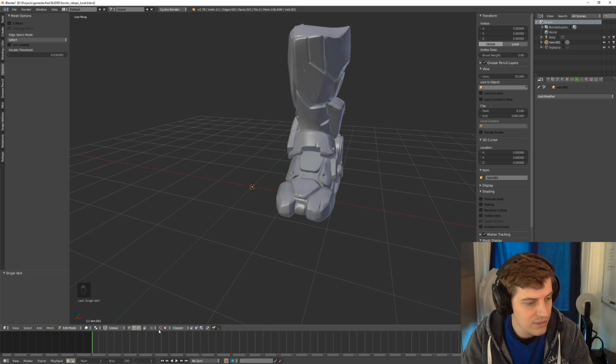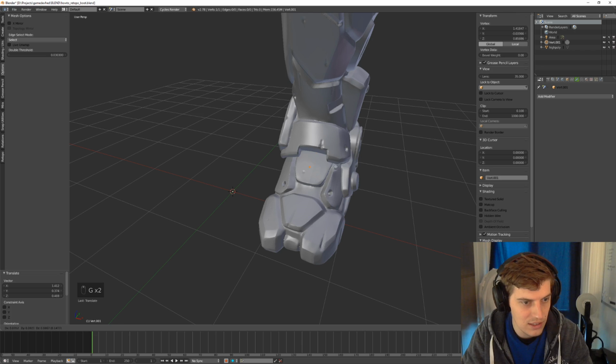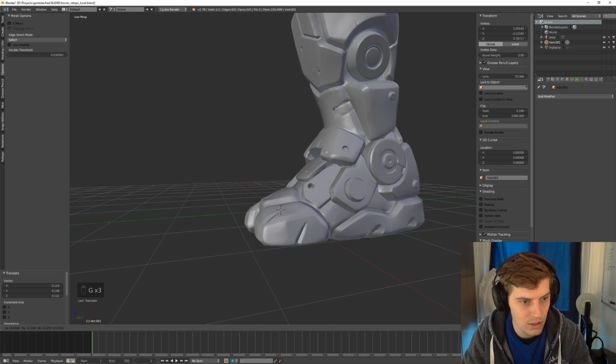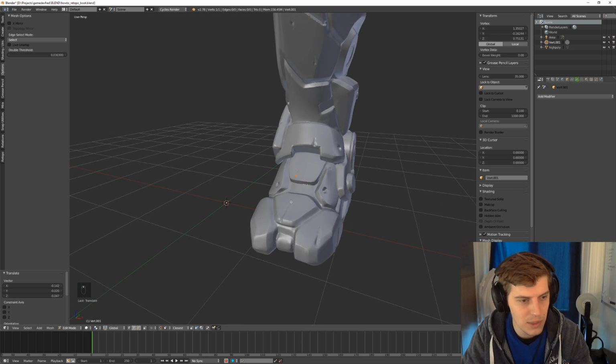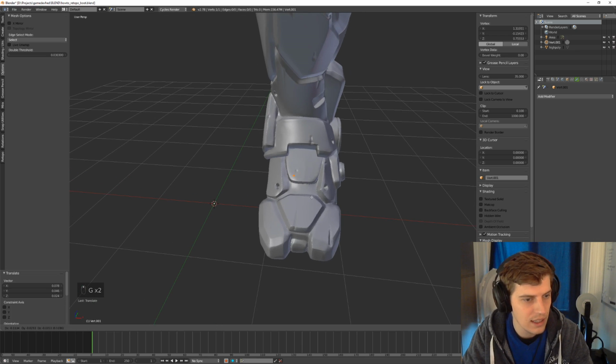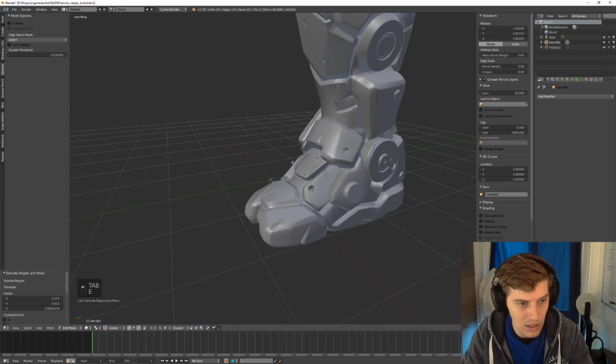So now that I have snapping turned on, set to face, closest, and all of these options turned on, let me just quickly show you what happens if I turn them off. Before I do that, I'll just position my vert, and you'll see that it basically is rolling on top of the mesh below. I don't need to select the target mesh or anything like that. It's basically just snapping on any kind of geometry that it'll find in the scene. Sorry. So I'll extrude, and then I'll go into edge mode and extrude again. And now I have a face.